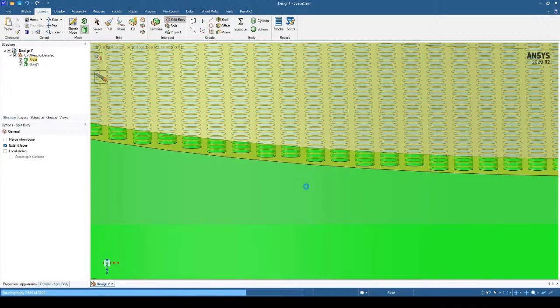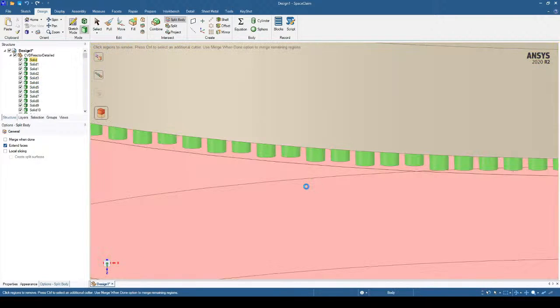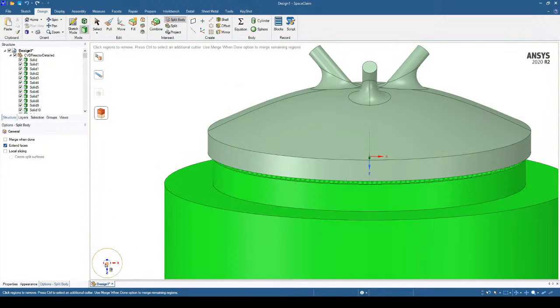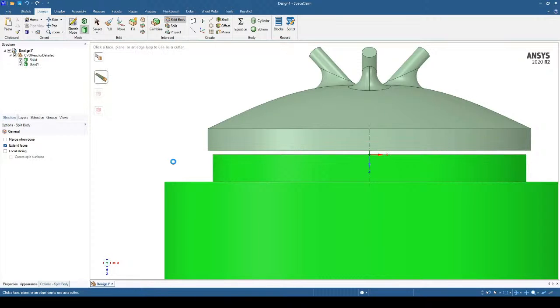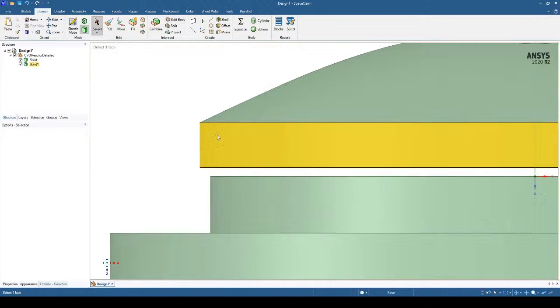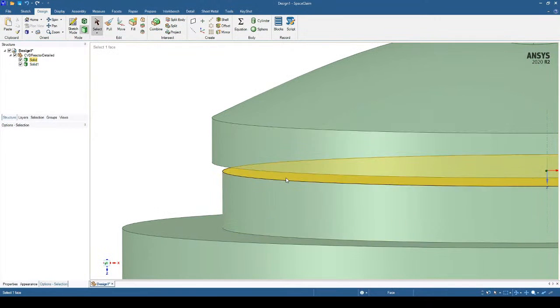The volume will then represent all of the shower heads. We'll put in a specific porosity information in that area so that the flow is only allowed to go in the z-axis, and we have the right pressure drop, pressure flow rate drop through that area.